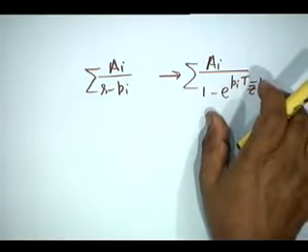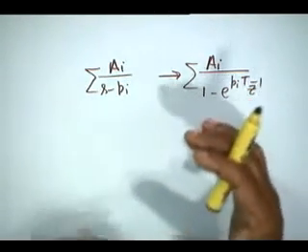And these are two ways of looking at it. One is the aliasing point of view, and the other is that aliasing occurs because we have no control over the zeros. On the other hand, in bilinear transformation, we transform poles as well as zeros. We transform the total function. This is one of the weaknesses of the impulse invariant transformation.